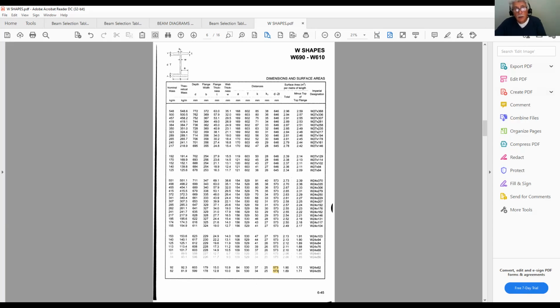Anyways, I was hoping to show you that the bottom flange goes in tension here, and therefore it goes from tension to, and this is the point of inflection. We have the same thing, and we're not laterally supporting the bottom flange, therefore the LU becomes the whole length of the beam.